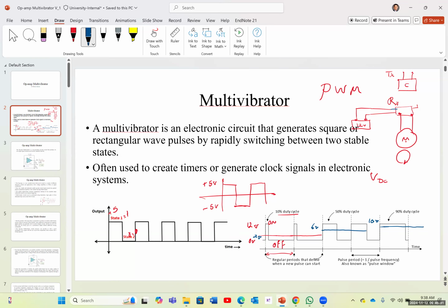Yes. So we have a high-speed switch. And if I connect that to a resistor and a capacitor, now I'm actually smoothing out. And if I give it a signal that looks like this, the capacitor is going to charge during the cycle and it's going to discharge. So you're going to have a voltage that is around the average of the time on and off.